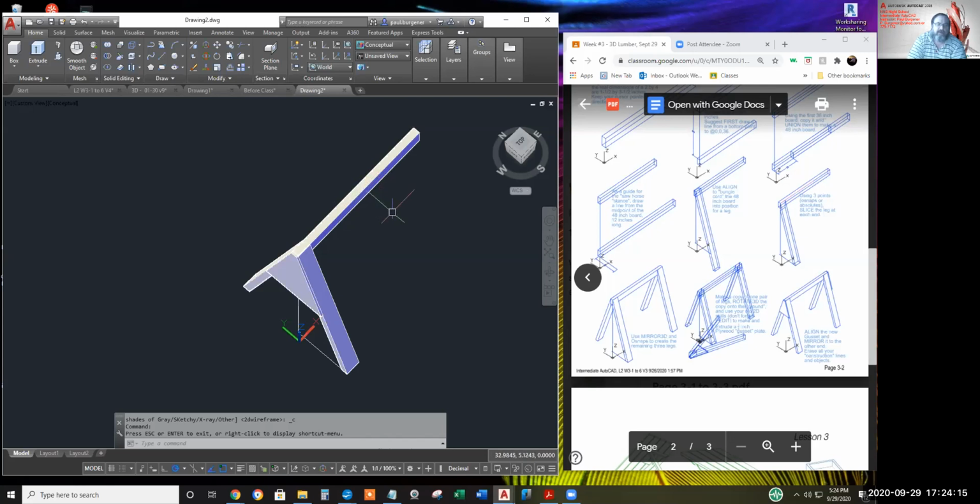You know, I think this would be a case where the 2-dimensional mirror command would be a click quicker. Drop down, select the 2-dimensional mirror command we learned. Select all 3 objects, shift and deselect that chalk line, which I should have erased already. Hit enter. All I got to do is specify any one of those midpoints of the top 2x4.